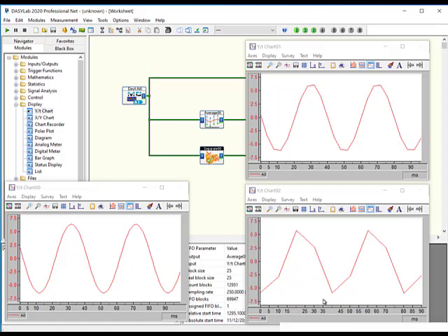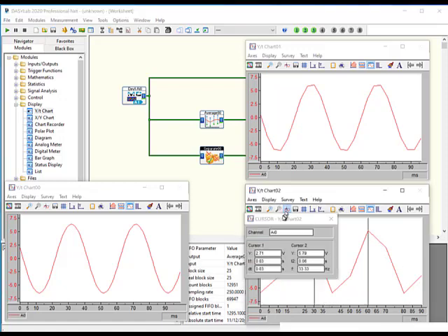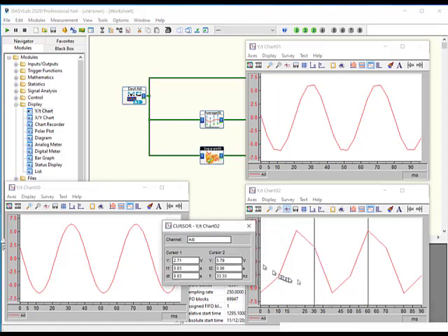It looks just much jaggier. I'll do the same thing I did. This is a 10 times reduction now. So I will put the cursor bars on adjacent samples, and it says the DT is 1/10 of a second or the frequency is 100 hertz.